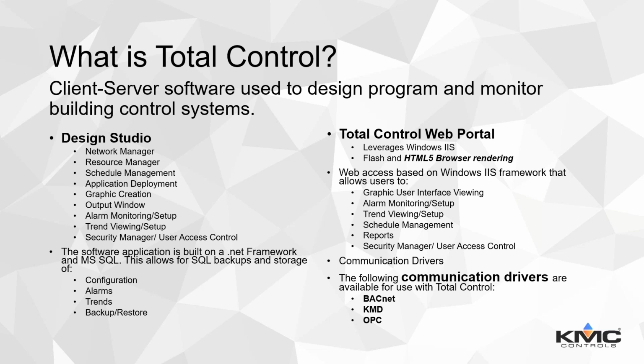All that is built, the application itself is built on a .NET framework, and it's stored in a Microsoft SQL database. So once you install TotalControl, you'll have a Microsoft SQL backend that is storing all the configuration, alarms, and trends for backup and restore purposes.